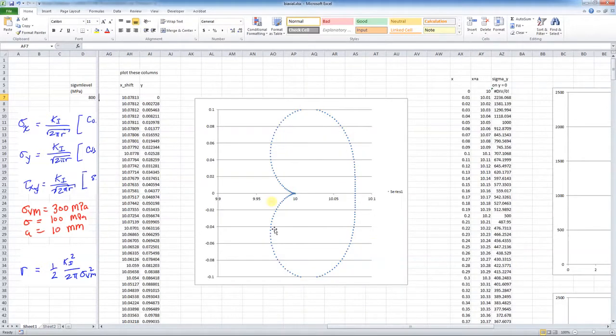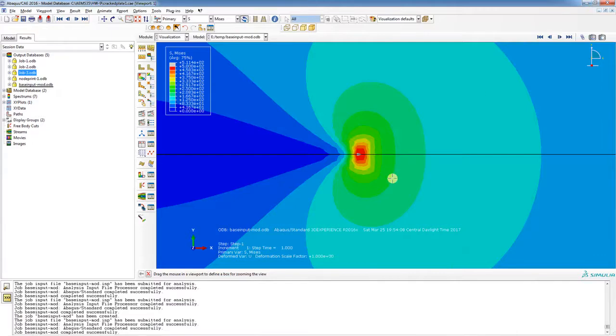Okay, so you see how that takes shape, and it's near the cracked tip. Remember, these are near cracked tip stress fields, so we want to be fairly close. But that shape does look very nice, particularly this kind of darker green shape. Now here you get some resolution issues with the element size and so forth. Let's see what happens if we animate this.